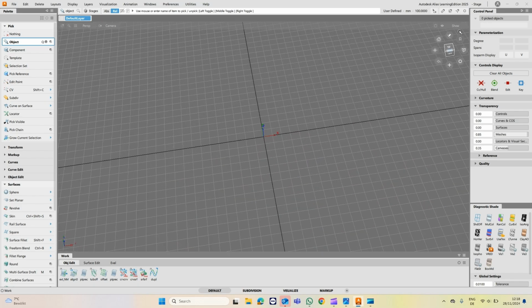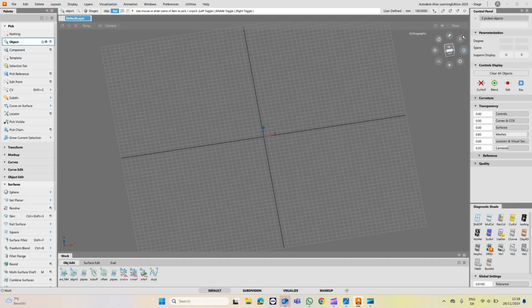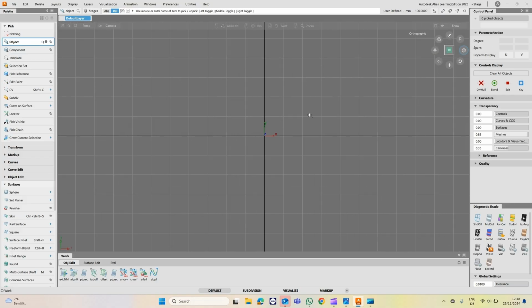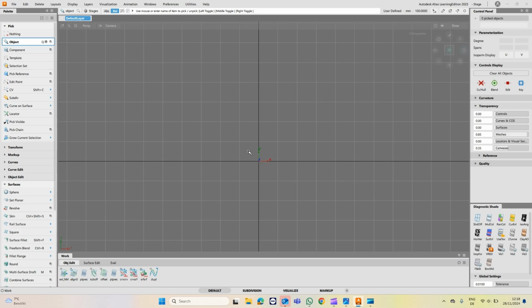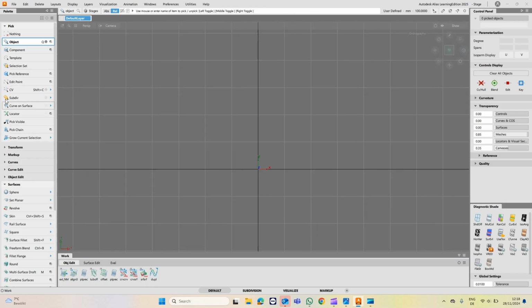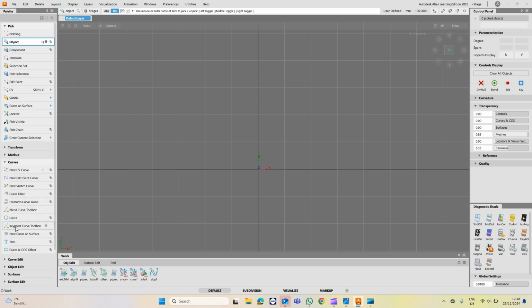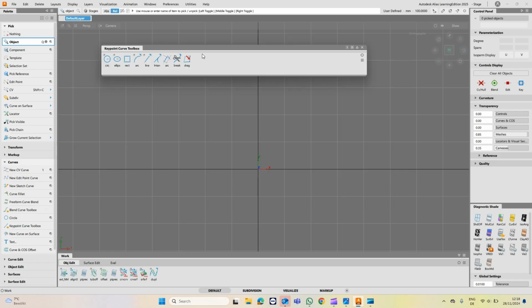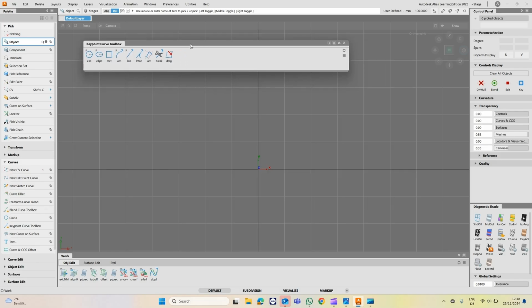I'm going to be working here using the orthographic views. So I'm going to be clicking here, going on to the top view, orthographic, and I want to center it based on the origin. What I'll use here for precision in curves is the key point curve toolbox, and I'll be taking the line here, and I'll alt snap it on the origin and go in the X direction.